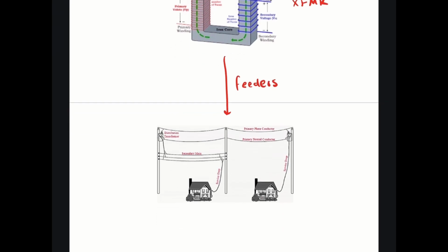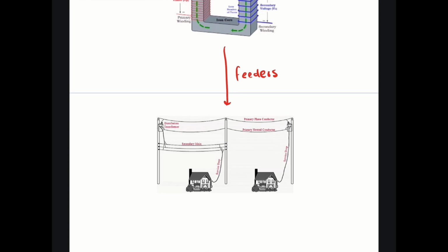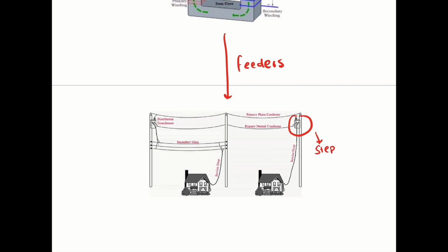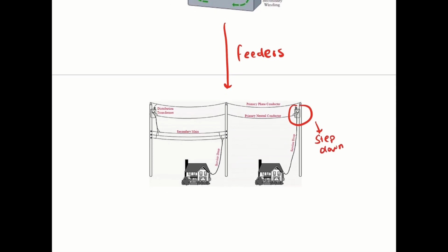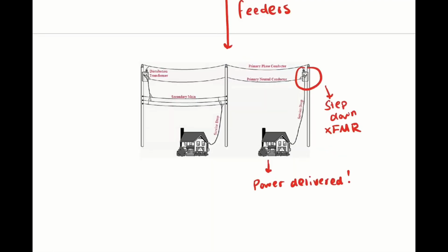Before power reaches the load areas, however, it must be once again stepped down to a proper voltage for residential use. Distribution transformers are used to accomplish this. The voltage varies depending on the customer and is typically 120 to 240 volts single phase for residential customers and 480 to 277 or 208 to 120 volts for commercial usage. After the voltage is transformed, power goes to the distributors, conductors that are placed at the low voltage secondary winding of the distribution transformers and carry power to the consumers.